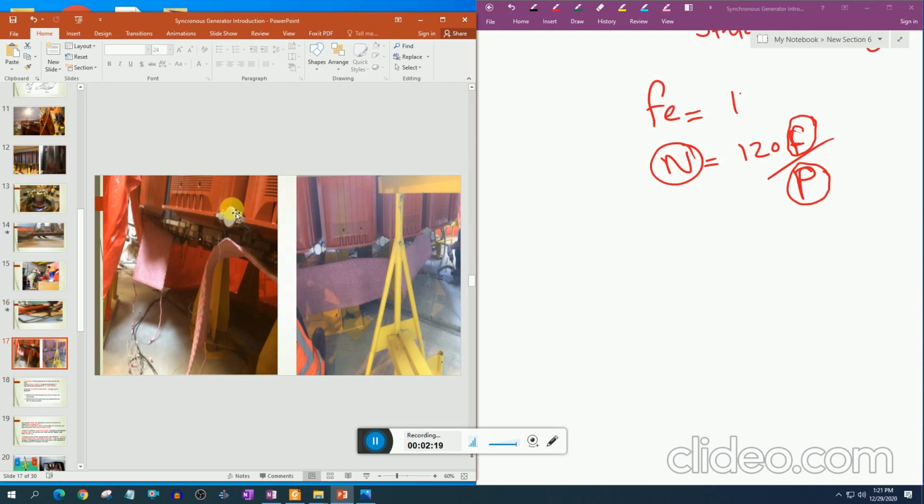So that's how the rotor poles look. I showed you the practical pictures of these poles. Now this process is used to heat the pole winding. In this way its resistance will improve, winding insulation resistance will improve, and poles will clear the winding test.